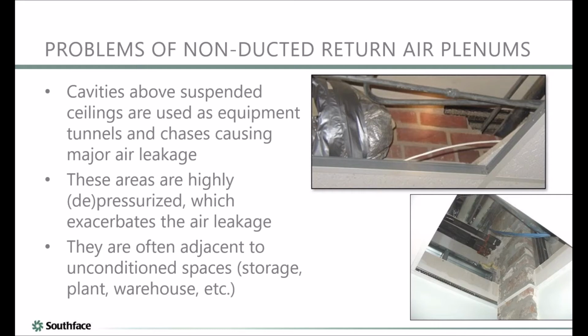Yeah, so the top picture is another commercial building I went to, which I think was built into the side of the grade, and I want to say it was a vented crawl space on the other side of that. Okay. So here, someone had to run maybe a refrigerant line. Mm-hmm. That's kind of what that looks like. Right. They ran that refrigerant line through this wall. They busted out the bricks. No one's ever going to see it, but on the other side of that wall is a vented crawl space, and it was moldy in there. Mm-hmm. So you're sucking in humidity, and you're sucking in mold from the vented crawl space into this commercial building, which was obviously more than one story.